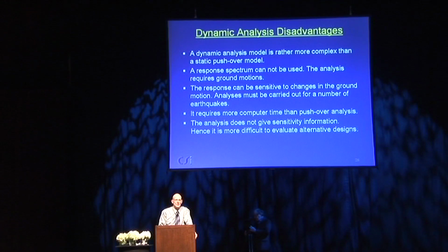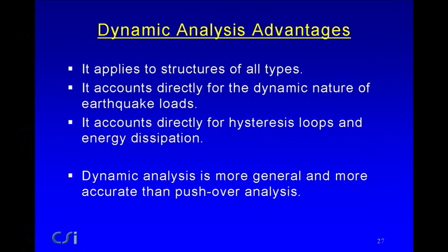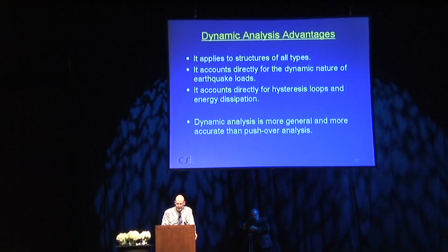And we've been through this before. If you use capacity design, it's a lot easier to decide what to do. If you haven't used capacity design, it's a lot more difficult. The advantage is that it applies to structures of all types. It accounts directly for the dynamic nature of earthquake loads, which can be important. It accounts directly for hysteresis loops and energy dissipation, or it should. If you run a dynamic analysis and there are degrading loops, your model should reflect that. So it's more general and more accurate than pushover analysis.